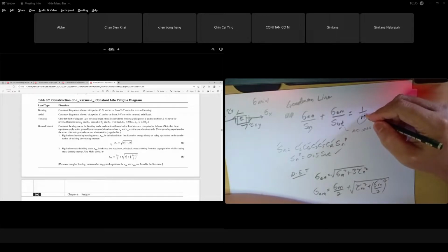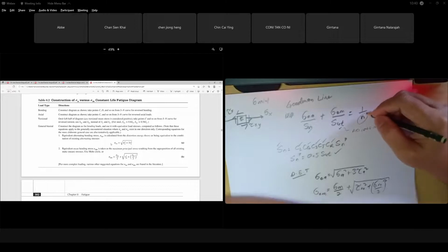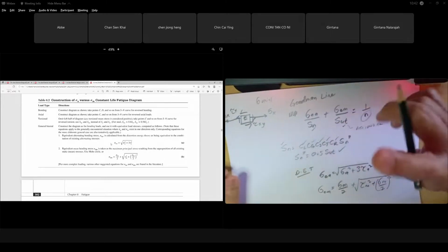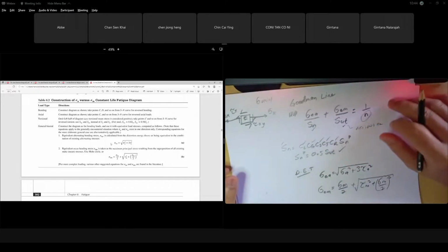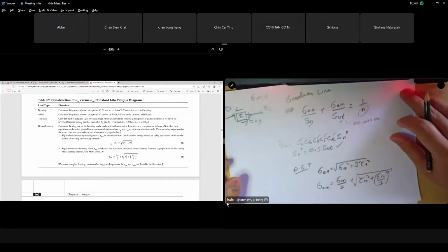So this will be your safety factor. Can you see my video? Then you put it in, and you get your safety factor. But another thing I have not considered, when we discuss the example, is the fatigue stress concentration factor.